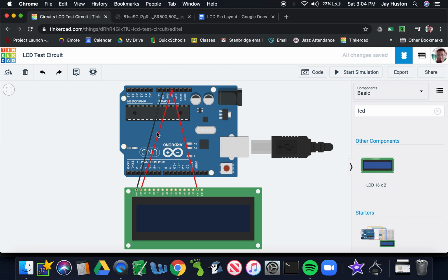So this powers the whole screen. This powers the individual cells that will build the words and numbers that I'm going to print. And this last one I saw, it says cathode. Hey, that's the out for LEDs. And since this is made out of LEDs, I'm going to ground that too. So again, you can choose any ground. I'm putting them all on the same ground.